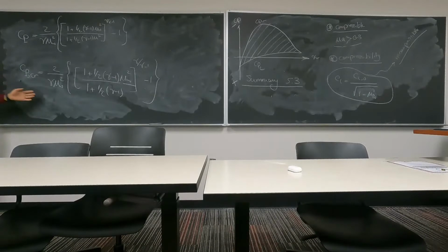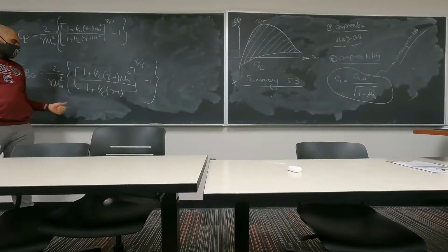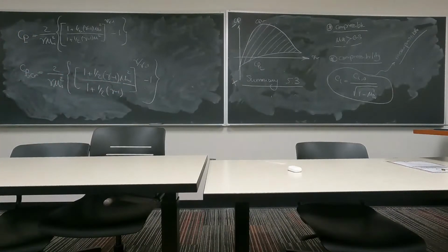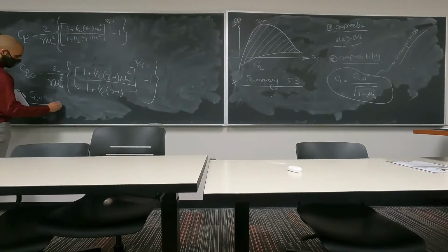So we're going to get the same equation. The only difference is that the goal of that equation is to find the Mach number instead of critical pressure. Let's say we calculate the minimum pressure using the incompressible analysis. So we have to include the compressibility factor as well. If you recall, everything else is exactly the same.